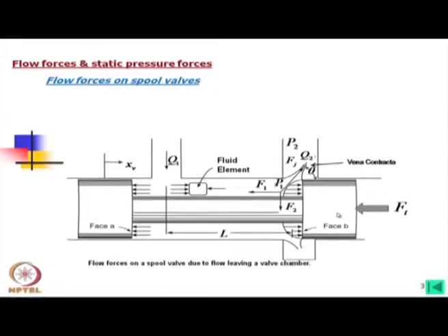While we are controlling the spool position, when it is opening we might be giving the force in one direction, but if it is overriding or over open, the force might be in the opposite direction. In a particular spool position, the force may act in both directions to keep the spool in that position.